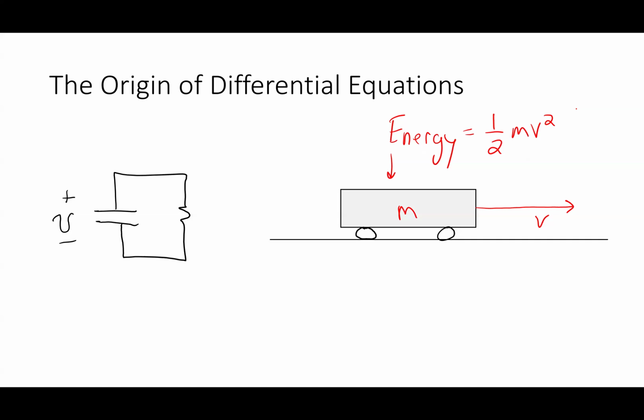But if you look at an outlet and you pull a plug out of an outlet real quick, sparks. You'll see a spark. What's the spark? Well, in that circuit there's an inductor and there was some current in that inductor, right? So you learned in physics, 1/2 Li squared is the energy stored in an inductor. If I make the i go from something to 0 instantaneously, the energy that was stored in that inductor has to go somewhere, right? So where does it go? It becomes light, right? Same thing's true with a capacitor. If I charged the capacitor and then stuck a screwdriver across the terminals, what happens there?